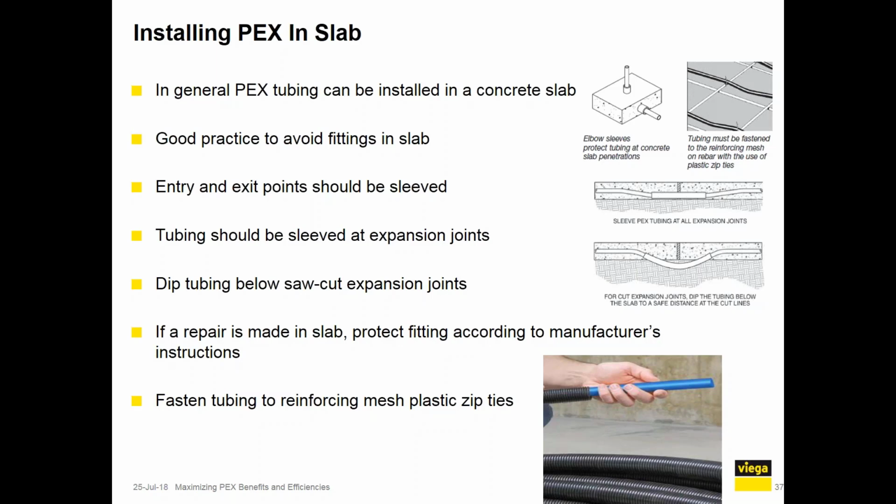And the benefit here is that you can put this sleeving with the PEX in the slab, and if you have repair or remodel issues down the road, then you're able to quickly pull that from the slab, pull the tubing out of the sleeving, and replace it as necessary. That prevents you from having to excavate dirt or chip up concrete if you have an issue down the road.